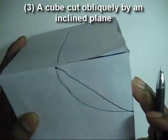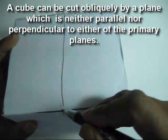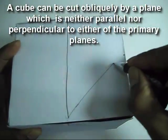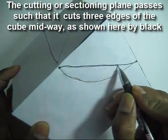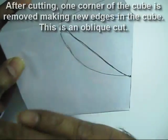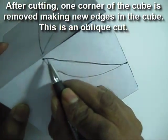Now the third example, a cube cut obliquely by an inclined plane. A cube can be cut obliquely by a plane which is neither parallel nor perpendicular to either of the primary planes. So this cutting plane passes such that it cuts the edges midway. 3 of the edges are cut midway, and this portion is removed after cutting. So this is called an oblique cut.